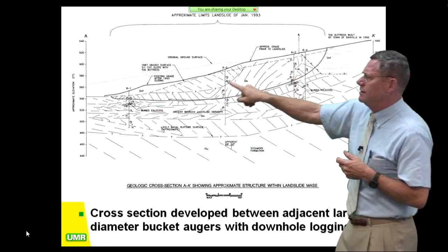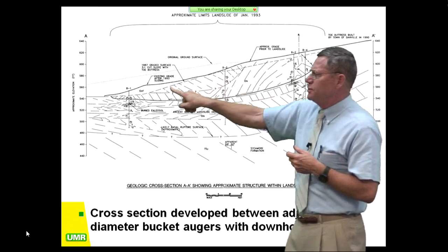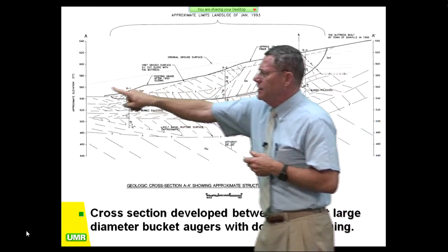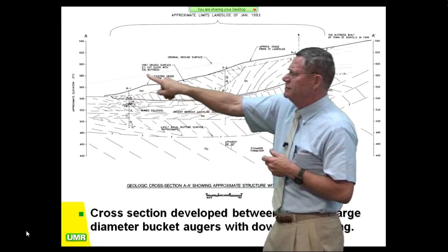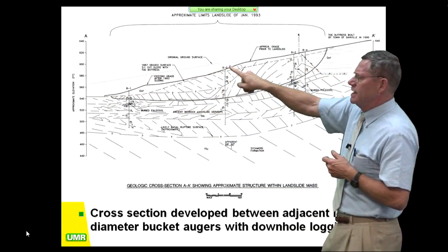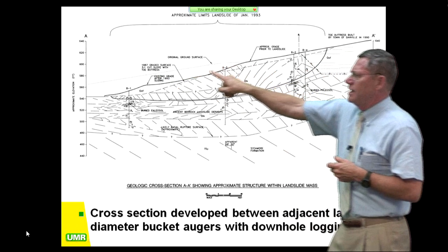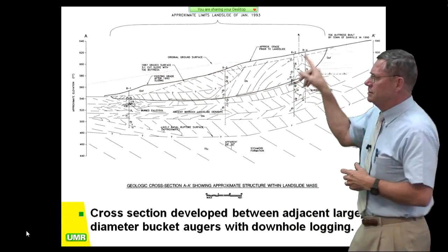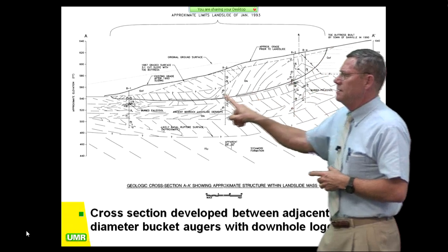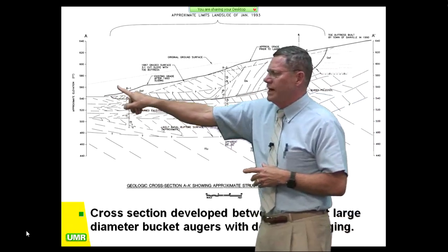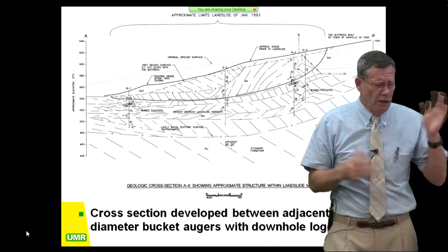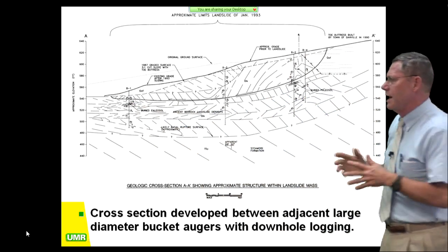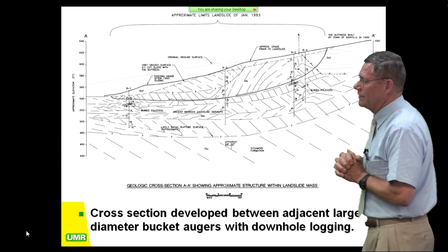Previous slide, a lot smaller. This previous slide had been repaired with a buttress fill right down here. The original hillside, which had been graded less than 10 years previous, was right there. And after they had done this repair, a couple years later, lots and lots of moisture, and this thing comes out and mows down about 8 houses, all of which are around $750,000 value houses at the time. This is about 1994, 95.